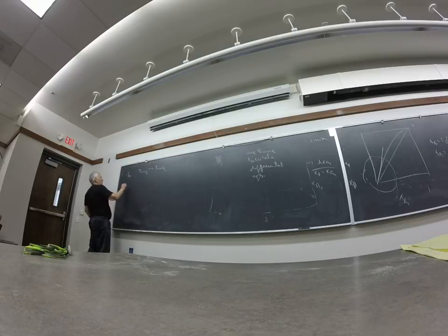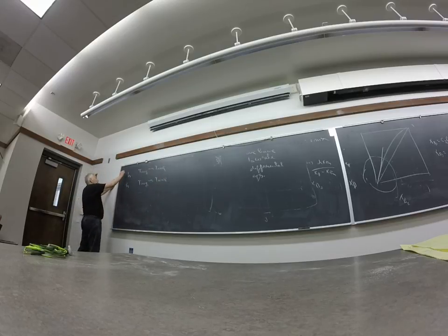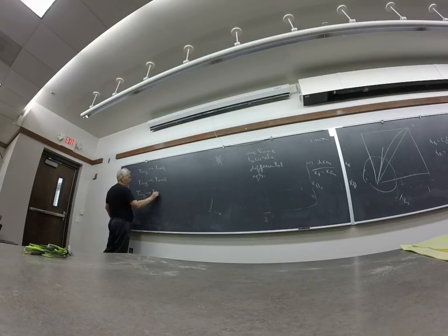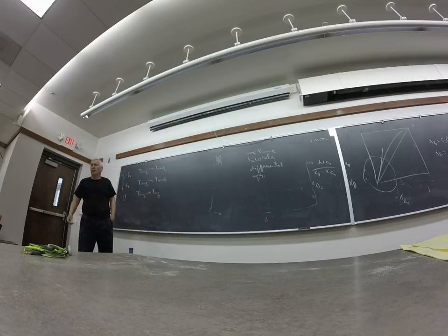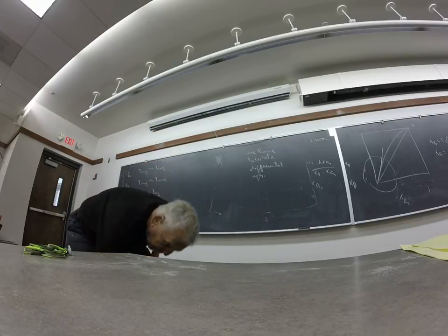And there's going to be another heat transfer coefficient on the other side, which is going to tell me how fast heat transfers from T average to T wall. And then I'm going to try and put these two h's together some way and get something called U, which is going to tell me how heat transfers from T average to T average. Okay, so right off the bat, this brings back great old memories, right?